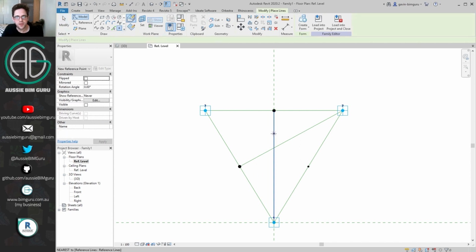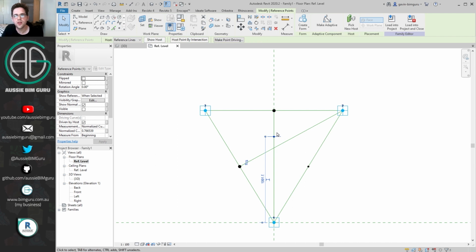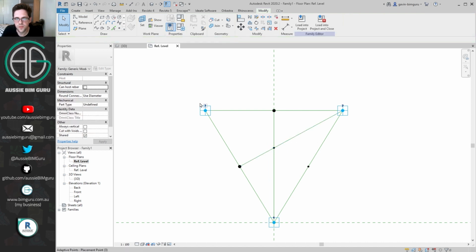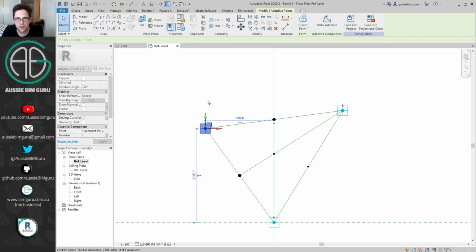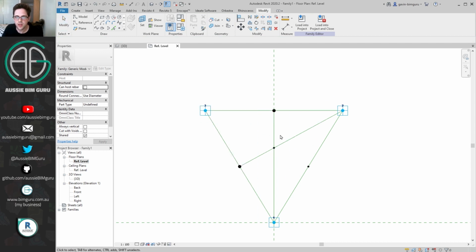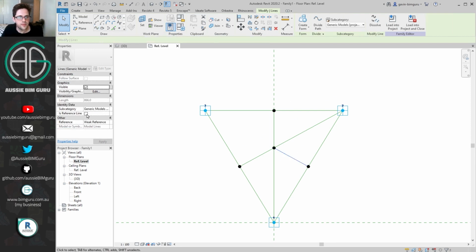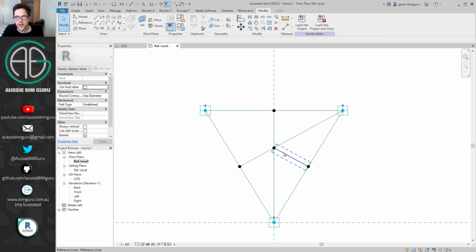And in this case, I'm going to place another point on this line here, but instead of just leaving it where it is, I'm going to select it. I'm going to host this point by intersection. So I'm going to host by the intersection with this line. So now this point will always remain at that intersection, no matter what shape my triangle takes. From here, I can just connect this normalized parameter point with this intersection hosted point. There we go. So we now have most of the framework we're going to need to do the basics of what we're controlling here.